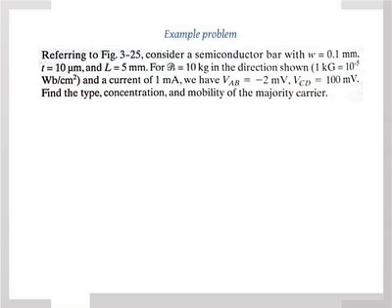To calculate the mobility, you need to know resistance. If you know voltage and current, you know resistance using Ohm's law. From resistance and the geometry of the bar, you know resistivity, which is a property of the material. Then you can plug it into this equation to calculate mobility. Okay. That's the progression, the steps you need to actually solve a problem like this. And you will get a lot of practice. So it'll come to you later on.